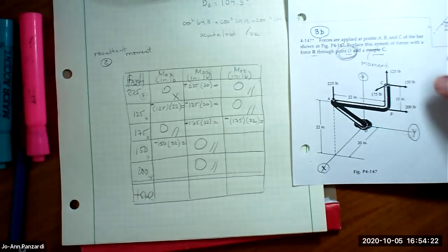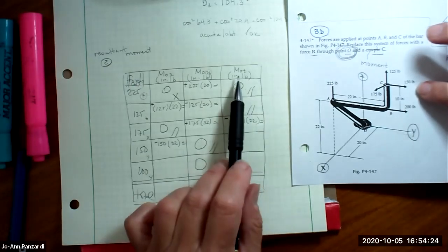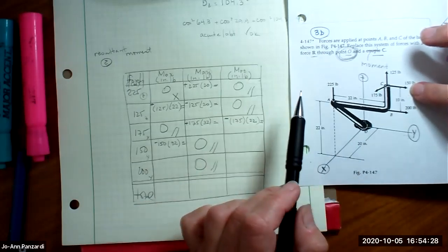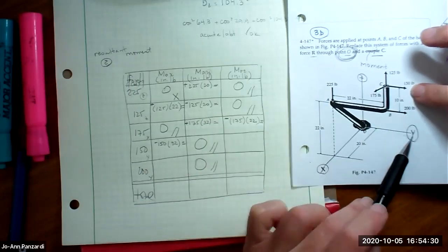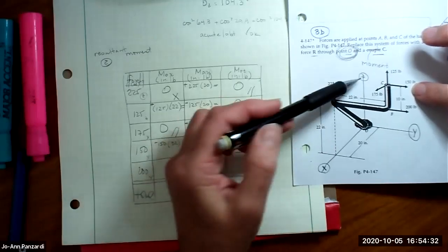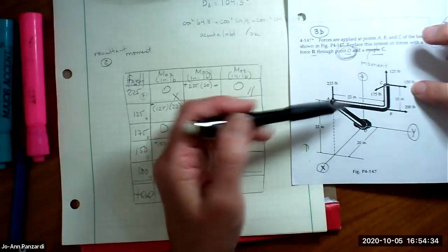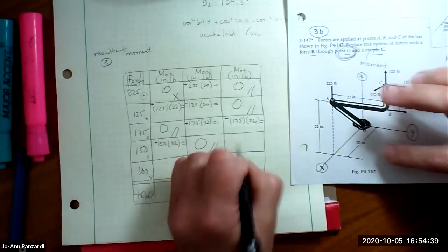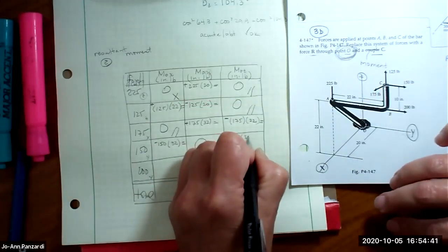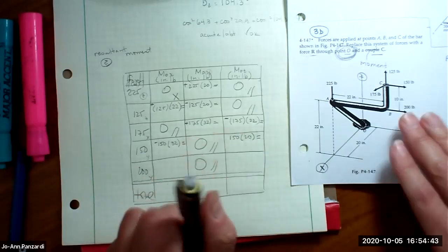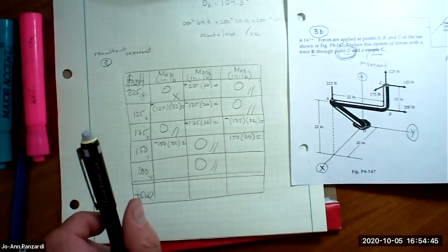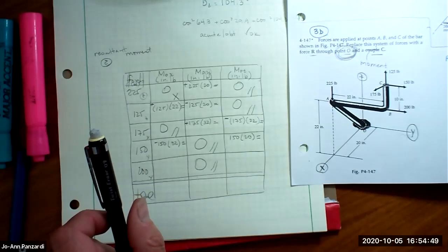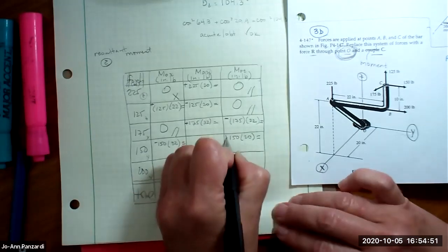And then I have the 150. Finding the moment about z, here's z. 150 is in the y. Z is in the z. And the distance has got to be in the x. How far is this out? It's out 20. So 150 times 20. Fingers go in the direction of 150. Palm goes towards z, and I get a positive z.